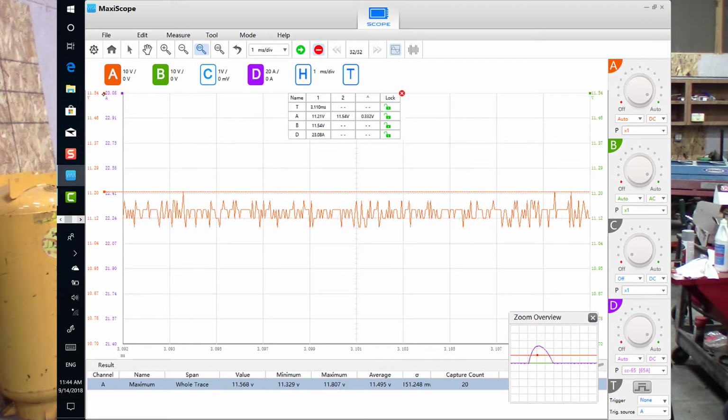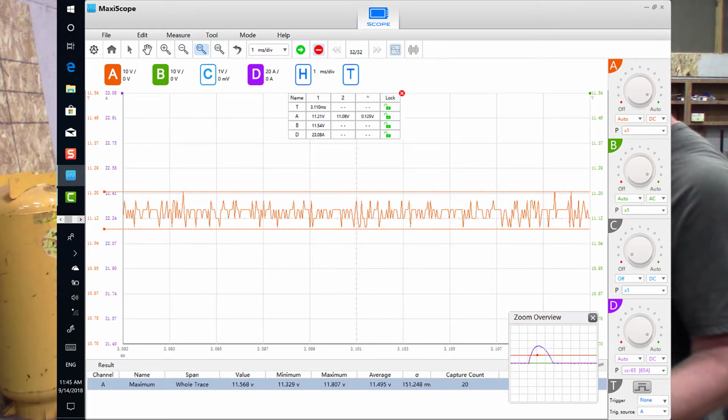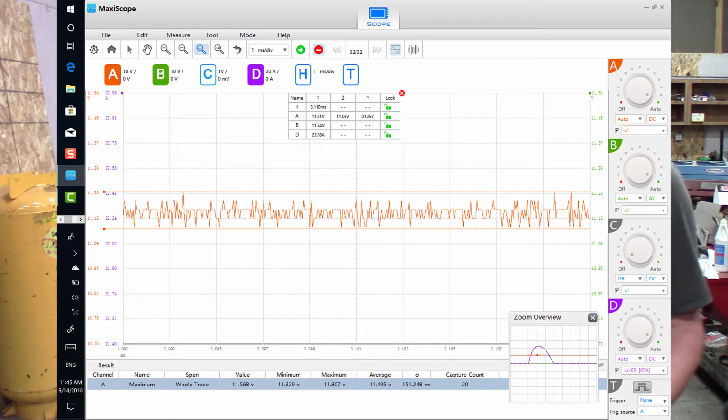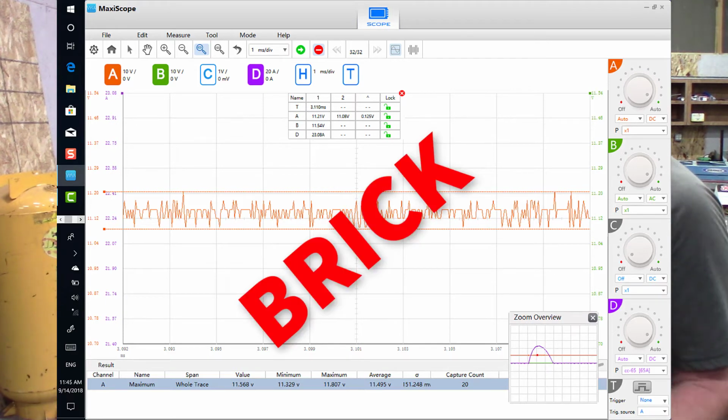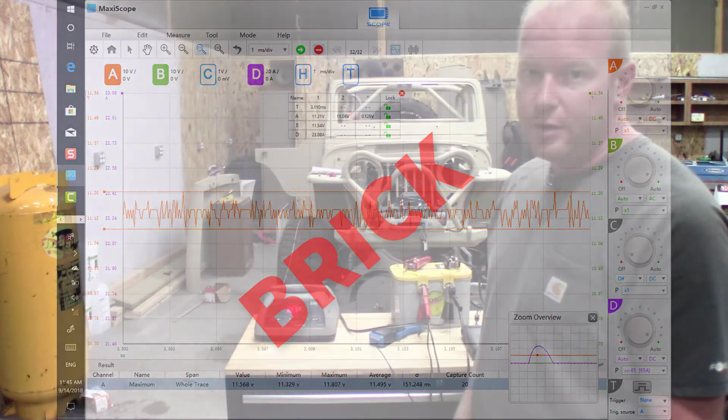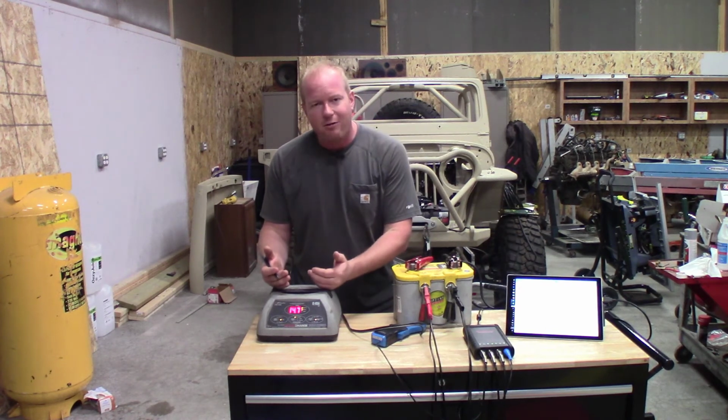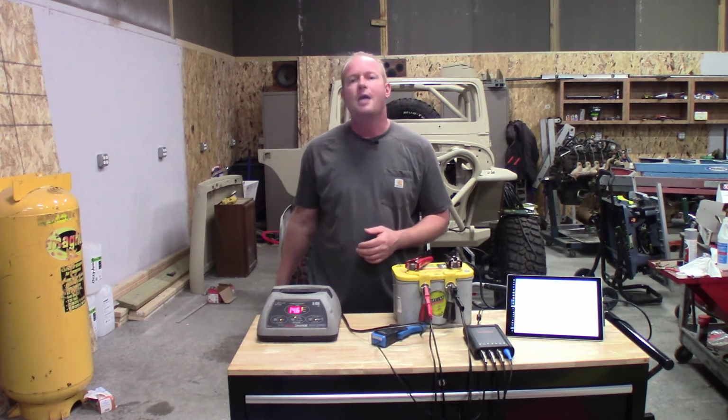We drop down to 11.21 volts, and on the low side, we drop down to 11.8 volts. Again, manufacturers require that we have at least 13 volts, 12.5 at the minimum, to be able to program a car. So we are way underneath that. So we know that a battery charger is not going to work.